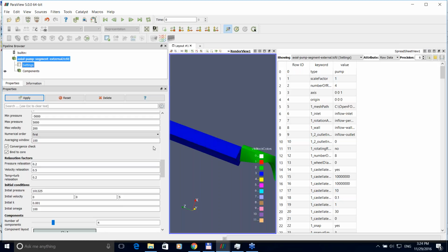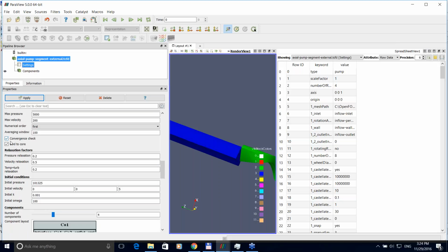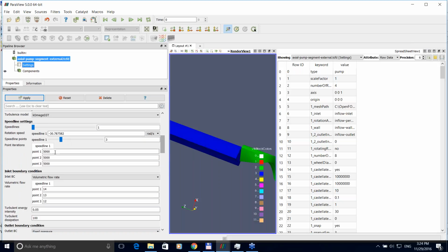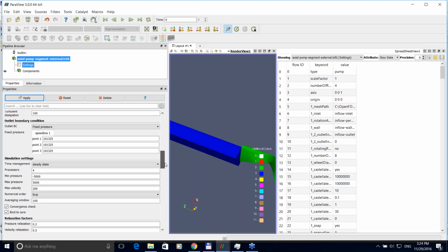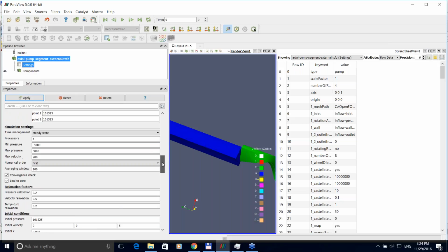so all quantities will be averaged within a window of size 100 iterations. There is a tool to check the convergence, so if the efficiency, the residuals, and other parameters have converged properly, it stops the iteration. For example, if we set 5,000 iterations and the convergence check is reached, it can stop earlier, for example within 2,000 iterations, so you can save time using this convergence check.